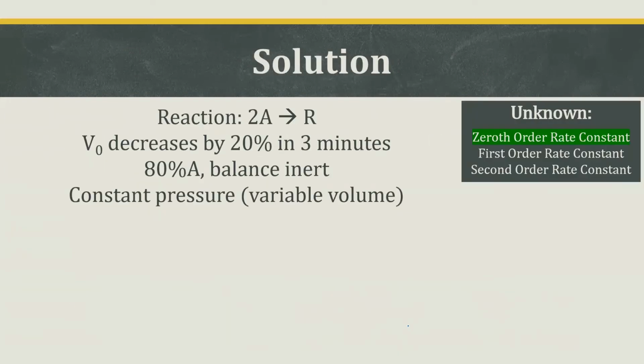Okay. But before we proceed solving, let's already look for the values of epsilon and the value of x. So for epsilon, that's just the moles of product minus moles of reactant all over moles of reactant times 1 minus inert, or in this case, we can directly use 0.8, since 1 minus inert refers to the fraction of moles of the reacting species. So you should get epsilon to be negative 0.4.